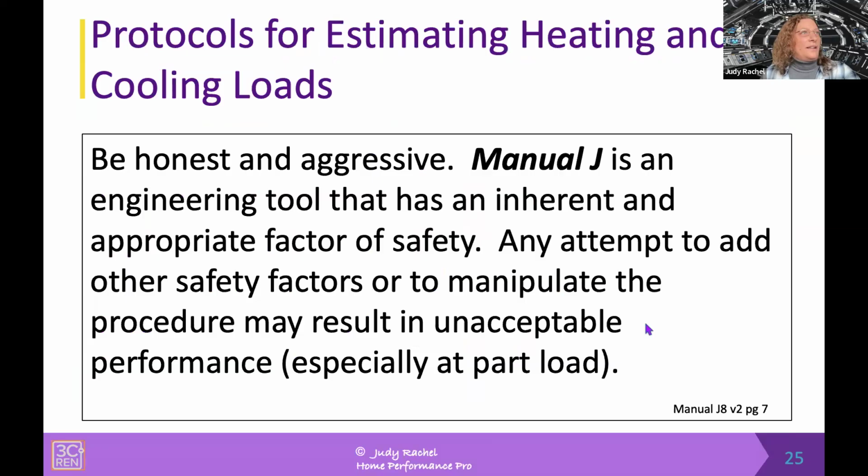So, the data collection, the site survey. Manual J states that you have to be honest and aggressive in terms of collecting your data. It's an engineering tool. It has what they say is an inherent and appropriate factor of safety. And any attempt to add other safety factors or to manipulate the procedure may result in unacceptable performance, especially at what are called part load conditions.